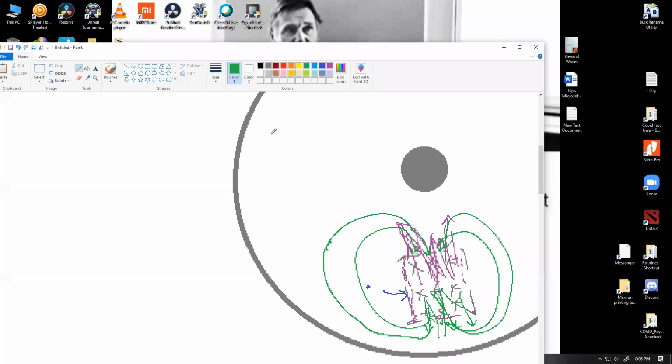This entire metal disk is a conductor. The number of electrons available is pretty high, and we are forcing all of those electrons all together. And depending on how fast this disk rotates, the force will be determined. So if the disk is rotating really fast, the force on the electrons will be very high, and the current will be also very high. And as a result, the electrons are gonna move on through this space. Now, here's the deal. Whenever the electrons are gonna move through the metal piece, they're gonna collide with the stationary ions, and there will be friction. Friction will produce heating.